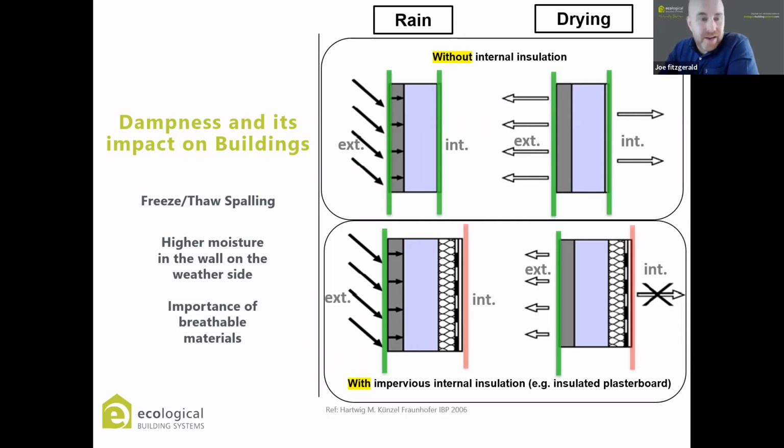So that's the reality. And the reason for a wall having more drying potential to the outside is the wind. The wind blows across the building and it encourages drying. As it dries the surface, more moisture moves into its place and it dries that too. The inside is slightly slower because you're just dealing with temperature and a small degree of air movement.